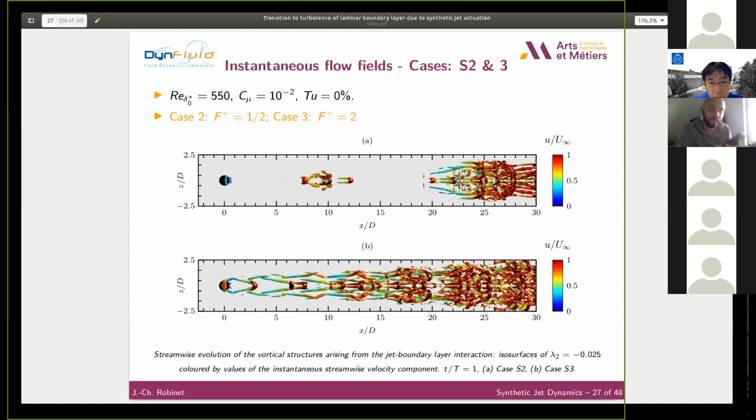And in fact, it's not really clearly described in the literature at this point, but it's necessary to have a threshold in intensity of the vortex. And in this condition, we can create a secondary arch of the hairpin, etc. When the hairpin is intense enough, on the center line of the hairpin we have a shear layer, and in this location we can generate inviscid Kelvin-Helmholtz instability, which destroys the hairpin. And at this time, you transition up. This is for the hairpin.